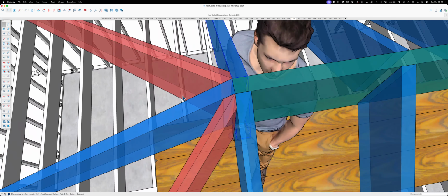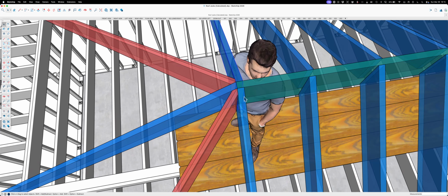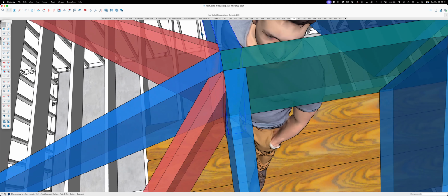Now we added some hips. And what's cool about hips, if you use the backing bevel, which, let me see, this is 23.09 degrees, it's really easy to do this. People go, oh, why would you waste all that extra time? Well, I'll tell you why. If you don't bevel your hips, then you have to drop your hip because you need this edge right here and this edge right here to plane across the top of these rafters.